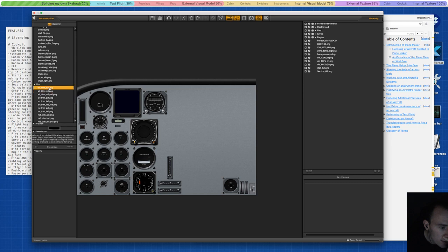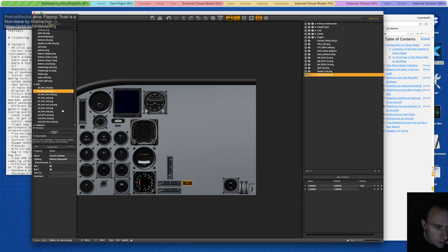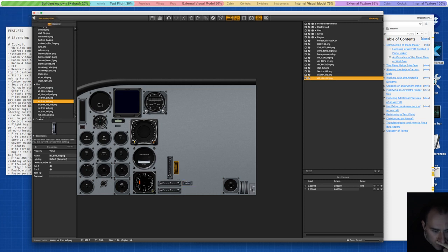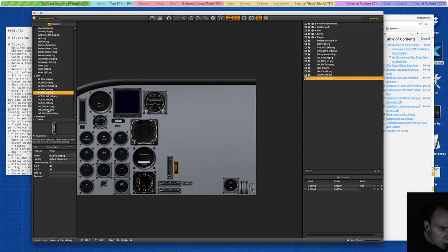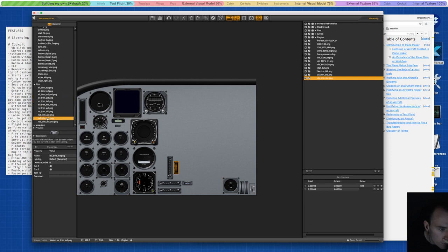Adjust this wheel to maintain level flight. You need to readjust trim depending on your airspeed or engine. Yes, but I'd like to see the actual setting of it. So that's aileron, elevator, trim, and rudder trim.